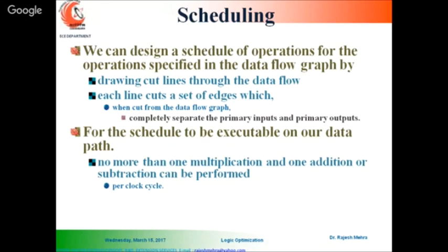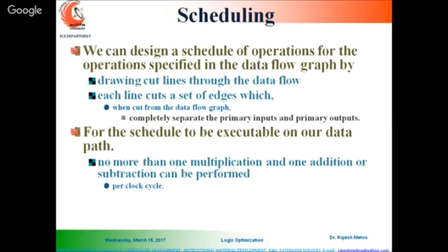Scheduling is nothing but scheduling different operations at different clock cycles. If the first clock comes to your system, which operation will be performed, add, multiply or subtract? That is your scheduling. Depending upon your requirement and input clocks, you decide which operation will be performed first.